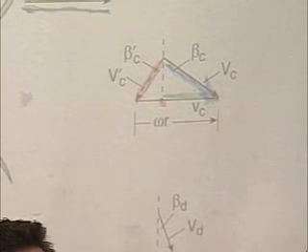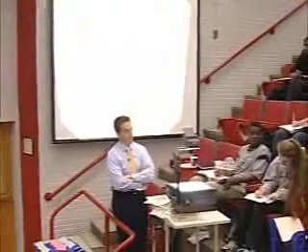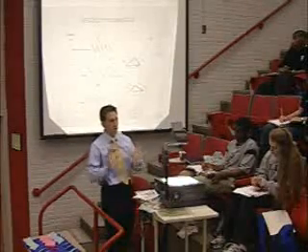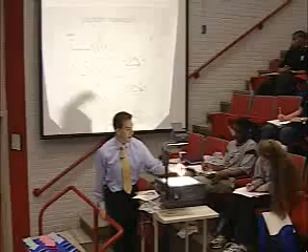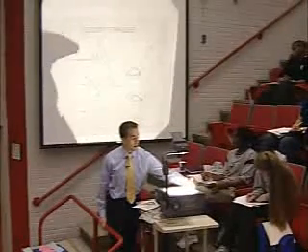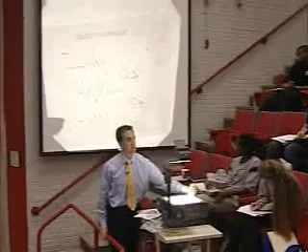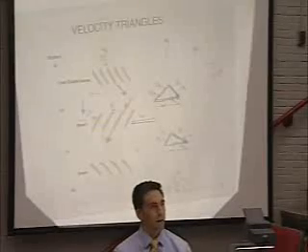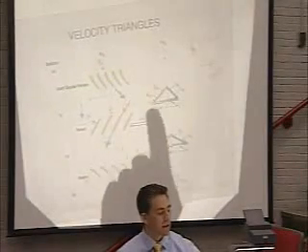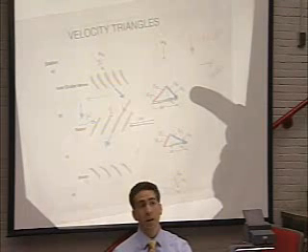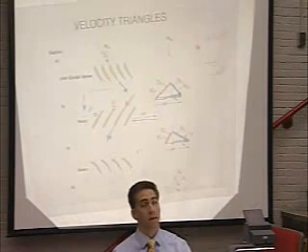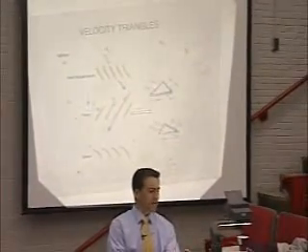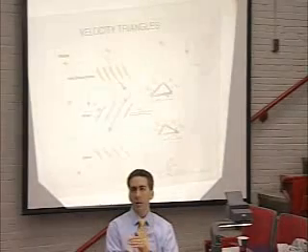Yep. Looks like before we had prime as our exit part and the non-prime is our entry. No, let me now explain the nomenclature, which I wanted to stay away from a little bit on this. The A, the B, and the C are for whether you're upstream of this blade row, this one, or this one. So that's what the subscripts are. The primes mean that you're in the relative frame. So this is the relative frame velocity. And the unprimed means you're in the stationary frame. That's what the symbols mean. I wanted to sort of stay away from the symbols for starters.